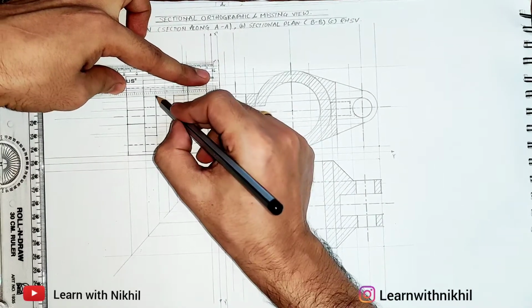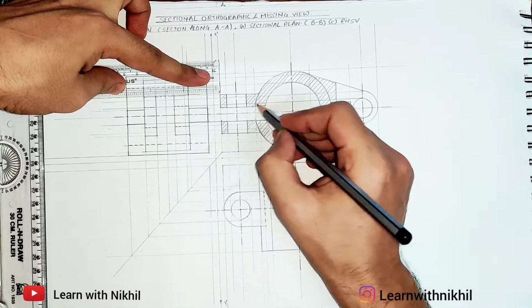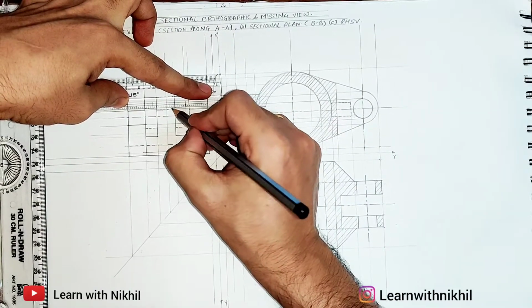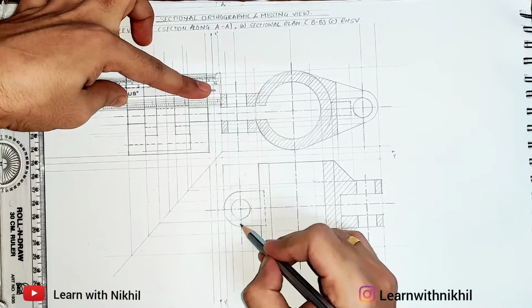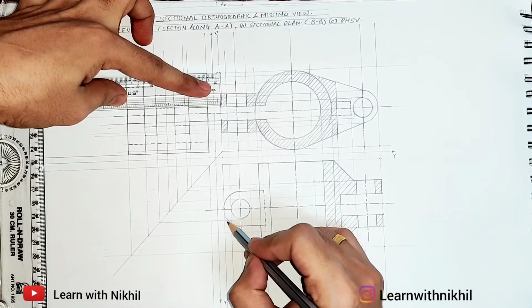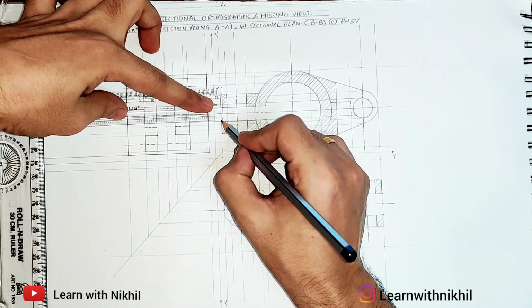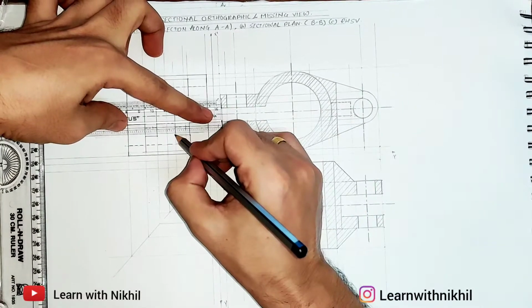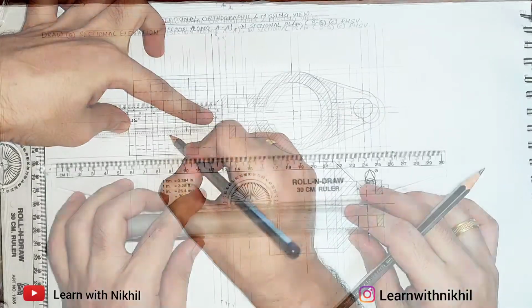This circle is hidden, this semicircle part, it is at the back which is hidden, so I am drawing it dotted. This circle and this outer semicircle both are hidden, so I am drawing them dotted with their projections from the front view and the top view.